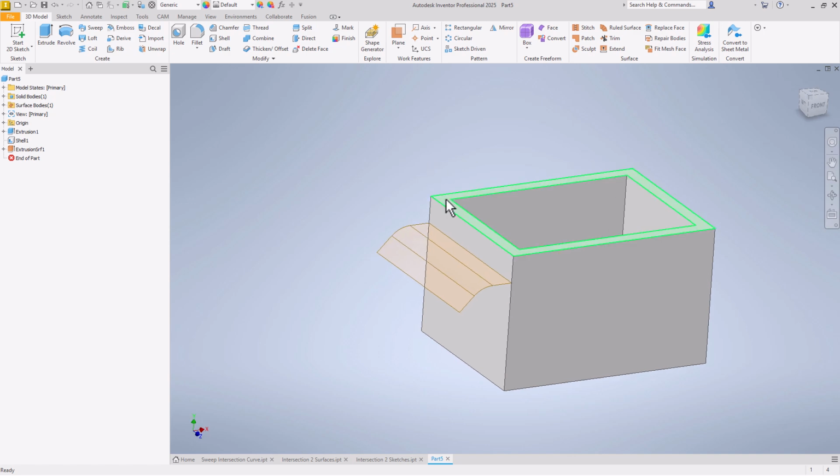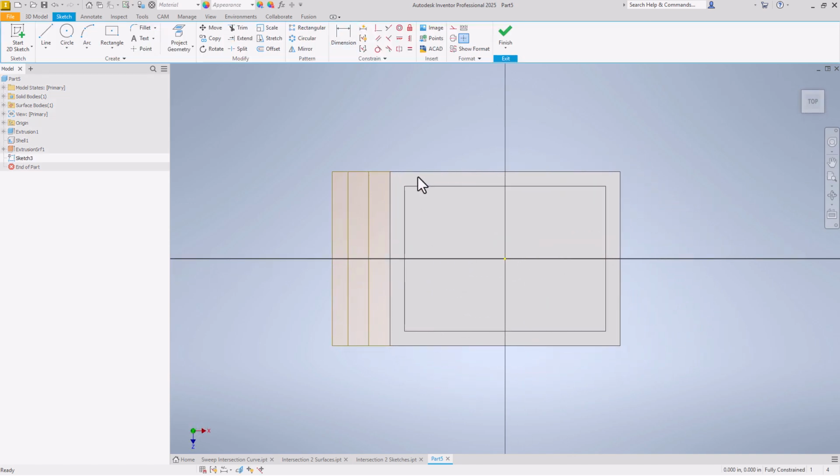And now let's create a sketch on the top of the box. And from this view, I'm going to create another profile, just a little more click and drag. Straight lines with some arcs in between. Let's give this some dimensions. Make it 2 inches wide. I want to be sure I keep the 1 inch dimension that I started with.